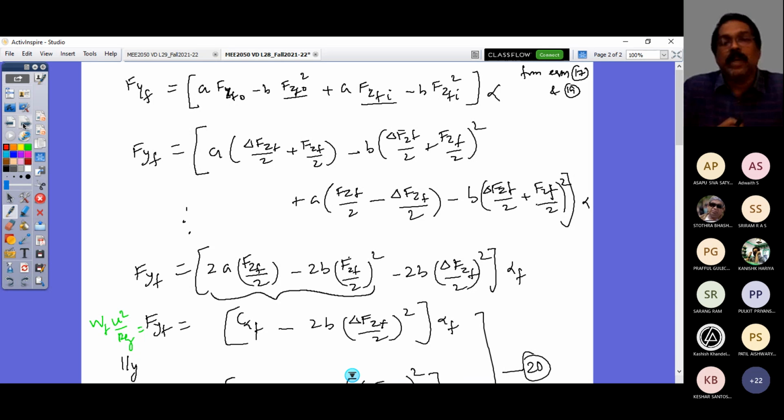That would give a way to look at not only the directional response of a vehicle, but also to lead to stability analysis, not only yaw plane stability analysis, but also the rollover stability of the vehicle and so on. So that is the reason why we accounted the suspension into our study. When you account the suspension into the bicycle model, the total mass of your vehicle is again considered as discretized mass, unsprung and sprung mass, because of the suspension.